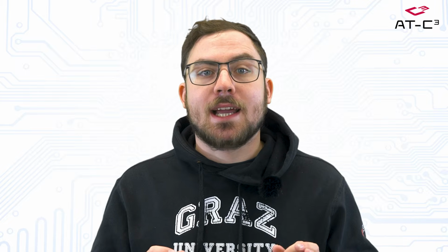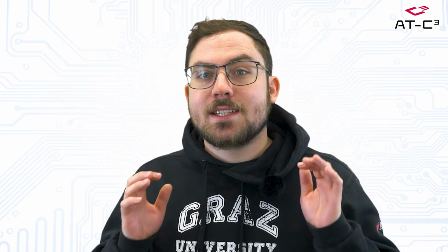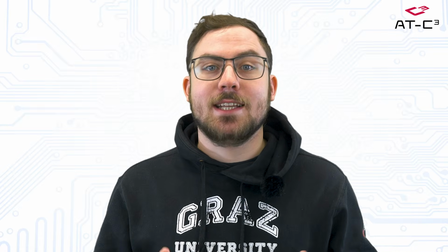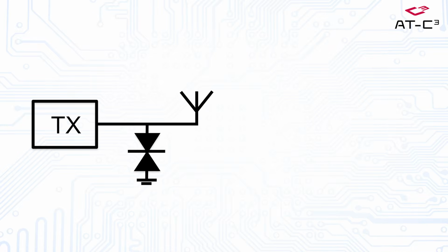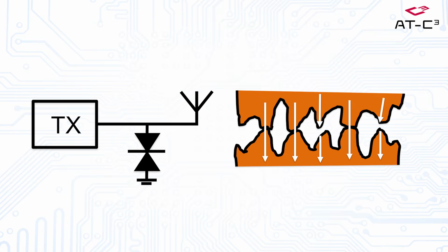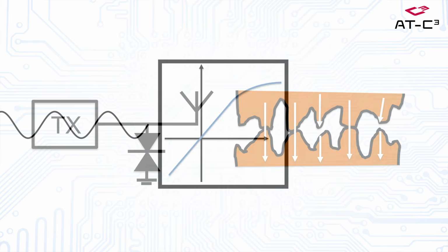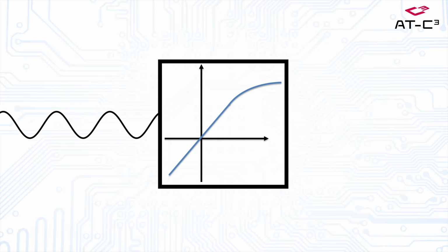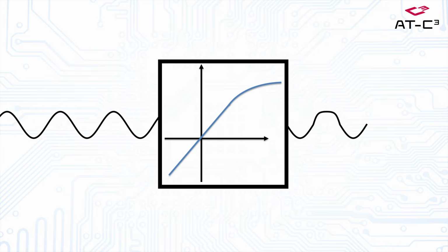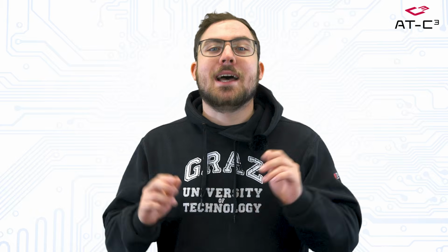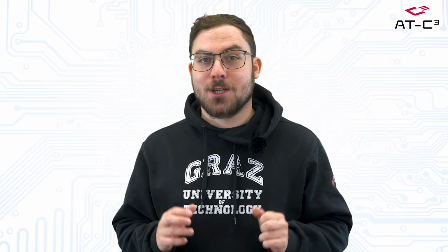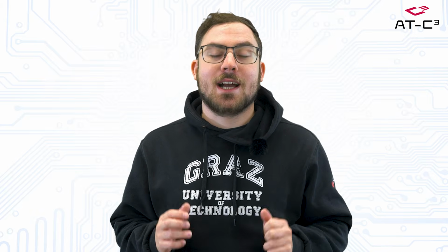Even if you design a system to be linear, it is very likely that some nonlinearity is still present, either because you add ESD protection in the form of a TVS diode or because of a non-linear contact that you may not even be aware of. In all cases, we now know that every time a signal interacts with a non-linear element, harmonics are generated. And now you know what harmonic distortion is, how to look out for it, and how to measure it.